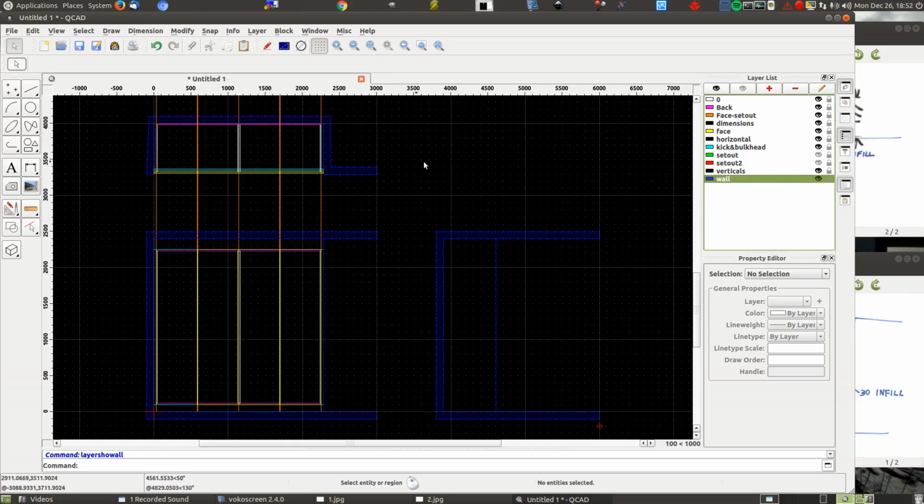We have to borrow dimensions off the plan view as well as the elevation, or front elevation. So this is going to be the left elevation, and in effect it's a section too. Like, it depends how you want to use the drawing, but in effect it's an end elevation or it's a section. You can choose what importance it is for you. Now section means what it would look like if you cut a hole through it, or cut a line through it. Okay, so I'll turn everything back on again.